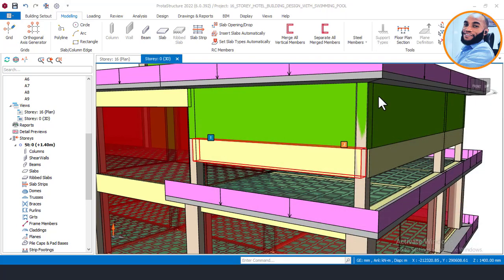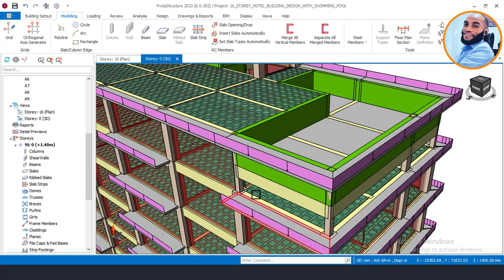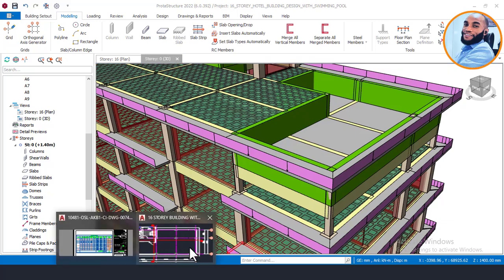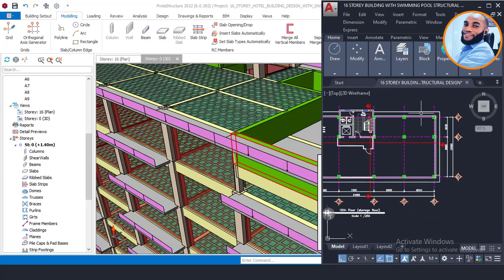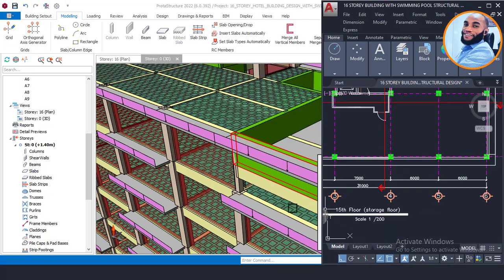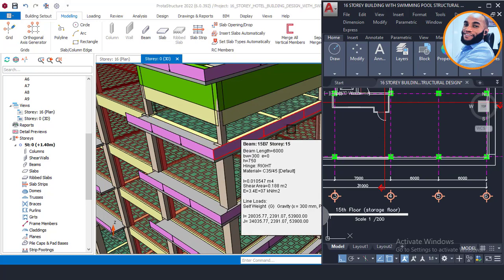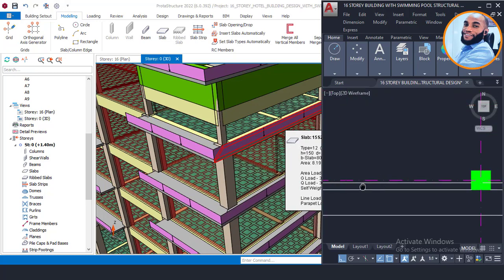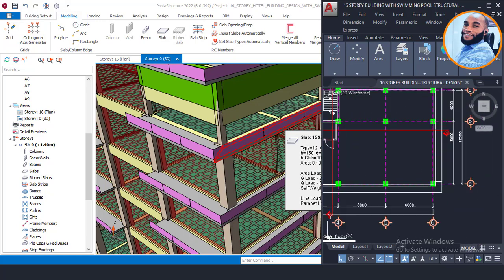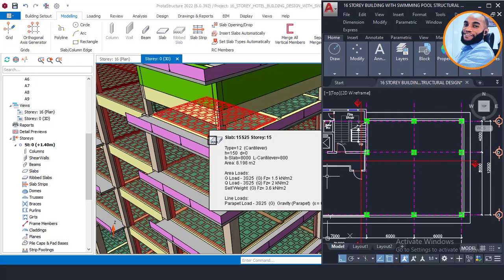Right now we will go over to apply the wall load on this area. But let's confirm if this area has wall load. From the CAD file again, you can see that basically there is no wall load, because this is the 15th floor. This beam here is the perimeter beam that we have around this place, and there is no wall load here. So there is no need for us to put wall load below the perimeter of the beam, which we have around this place here.